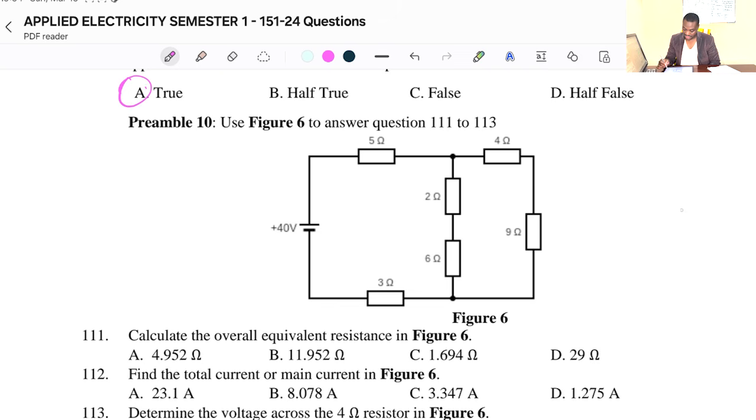We can see here when it comes to this figure that 4 ohms and 9 ohms are connected in series. So I can just come here, that will be 4 plus 9, 13 ohms. Then when you come to 2 ohms and 6 ohms, they are also connected here, so that will be 8. You add those up. Then after that, I have my...